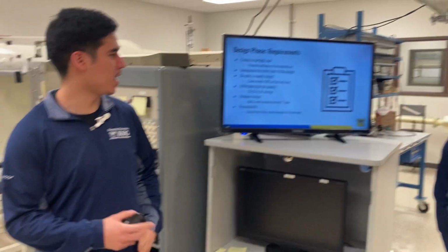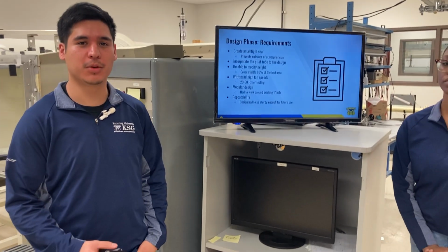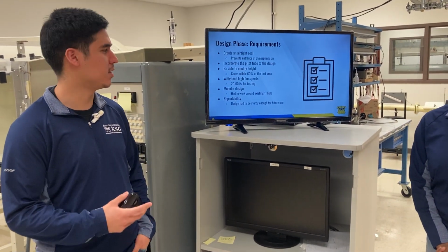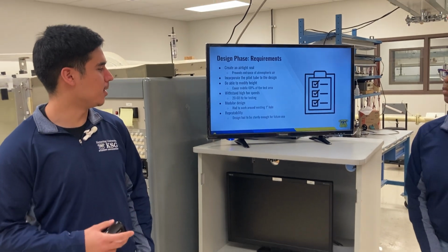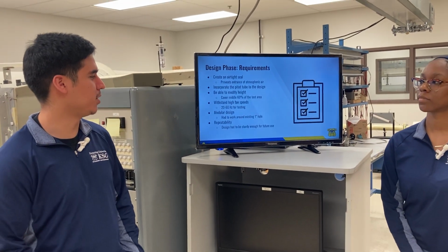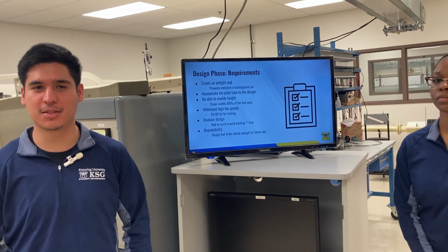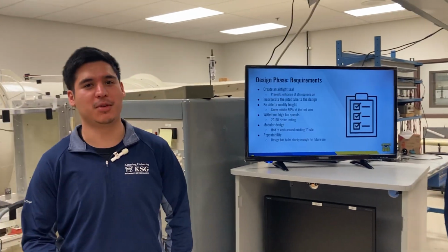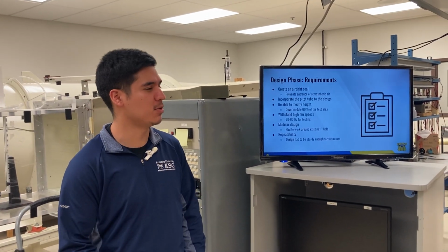We had to withstand high fan speeds, being that we were going to run between 20 and 60 hertz. We had to have a modular design because we were working around an existing 1-inch hole, and we had to make sure it was repeatable, being that it might be used in the future.